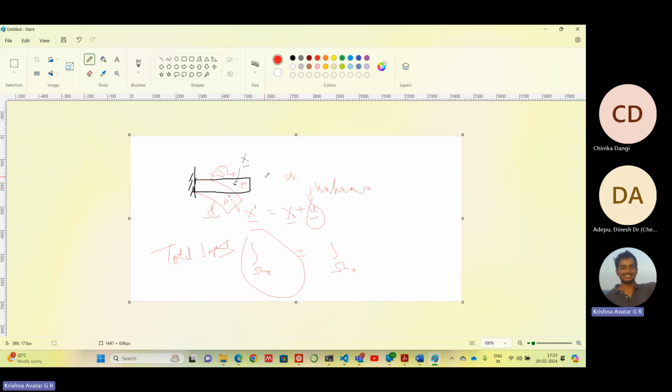In that case, we would like to progress systematically. If this body undergoes very large deformation, say something of this sort, then u is very large compared to x, isn't it, for problems like this? In that case, total Lagrangian formulation is not recommended. So we would like to keep changing the reference configuration, approaching this through a series of deformations.